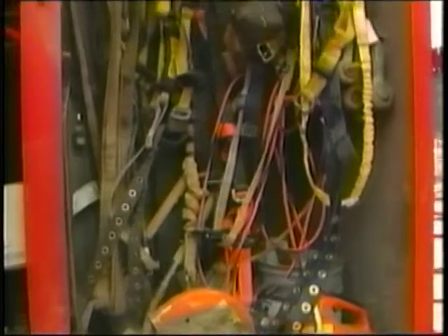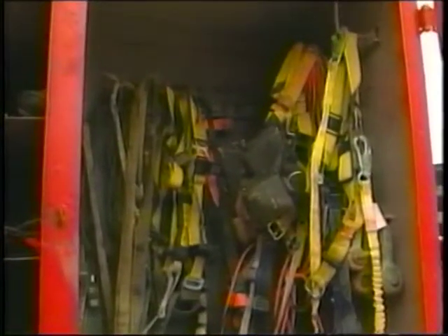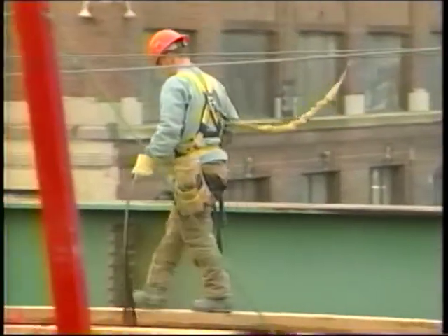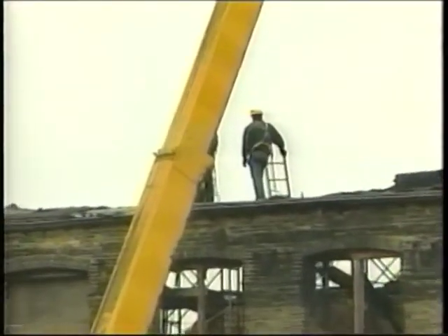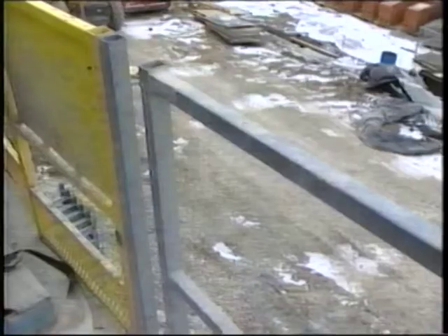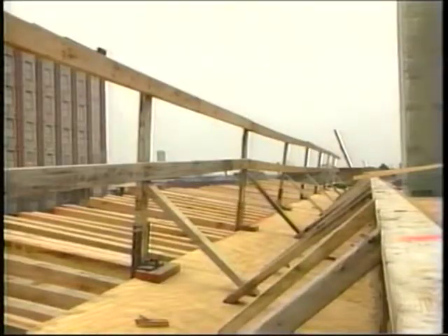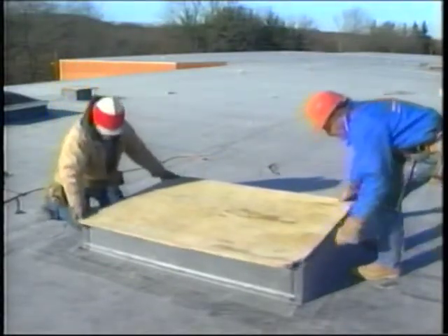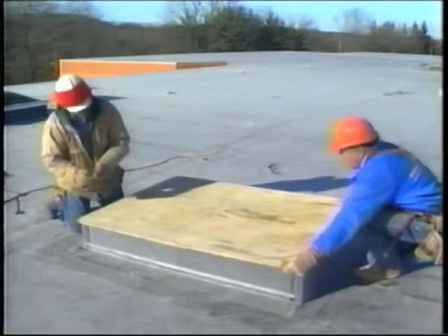Third, take advantage of the safety devices your employer provides. They're there for your safety, so you should use them. Your employer must provide some method of fall protection when you work at heights. Guardrails with toe boards are methods that protect you from falls. They also protect workers below from falling objects. Guardrails are used on scaffolding and around the perimeter of buildings. Covers must be used over floor openings to prevent falls.